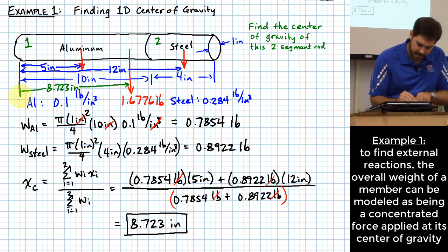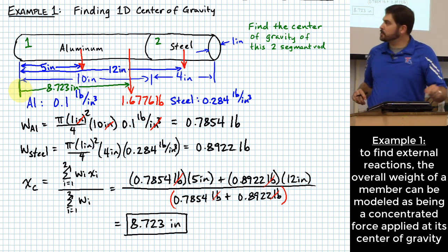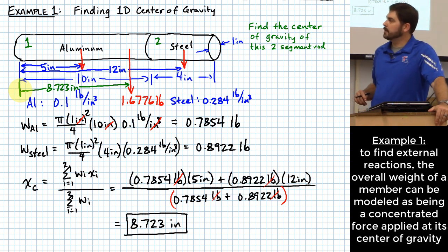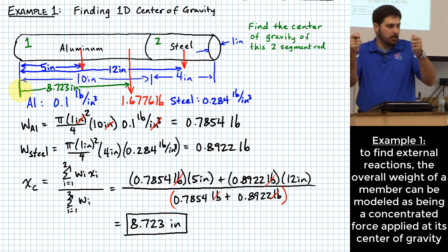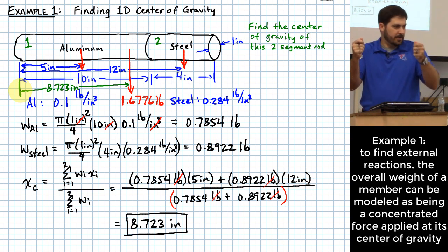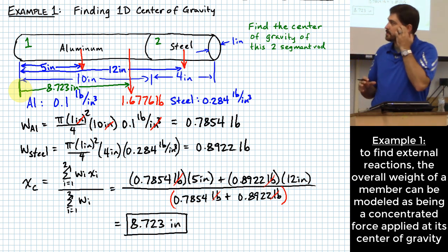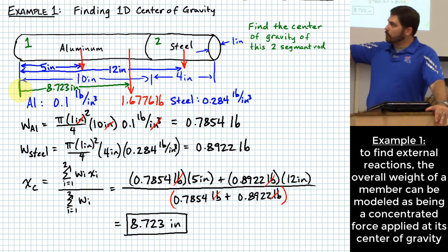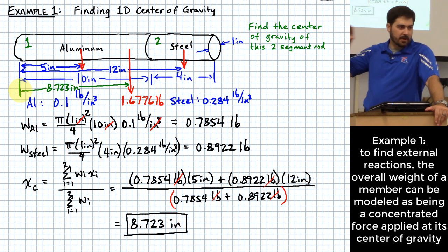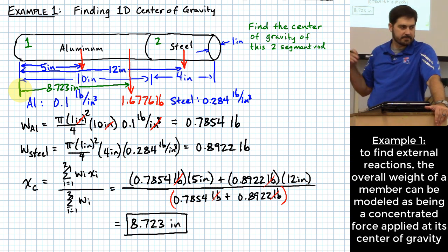away from the same axis that I did my original measurements with respect to, then that would cause the same reactions on the piece that's holding it up, right? I don't have to look at individually the reactions of each one. I basically found where the weight of the overall piece should be centered so that it causes the same kind of reactions at the supports. Does that make sense?